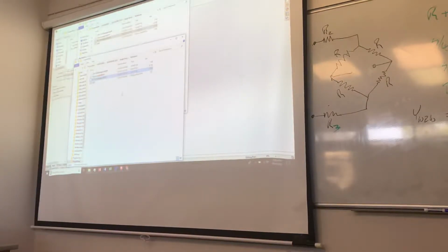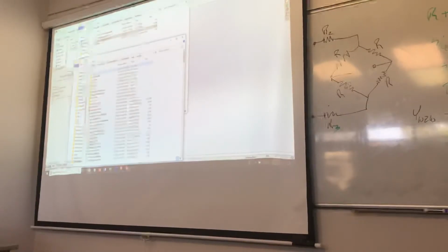And then I get to go figure out where I really want to put it. I want to say C program files, back down to SolidWorks Corp, SolidWorks, language, English, weldment profiles.